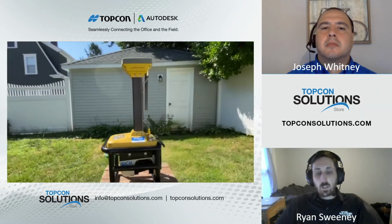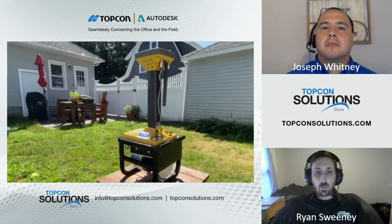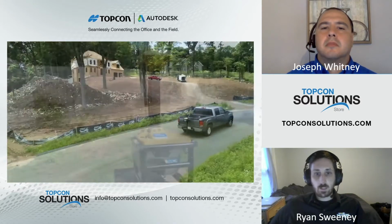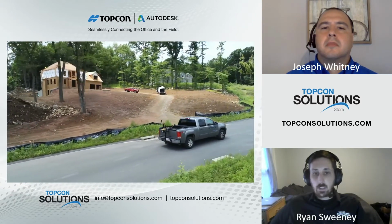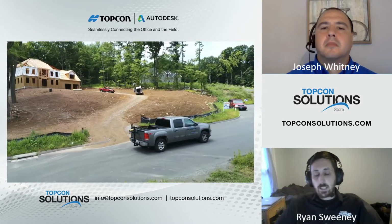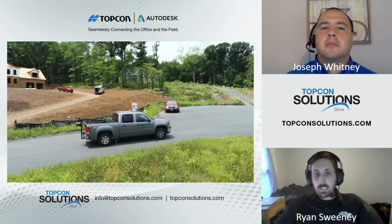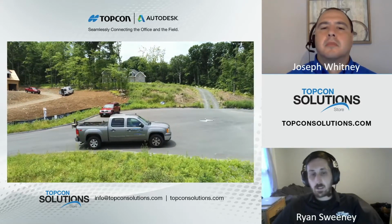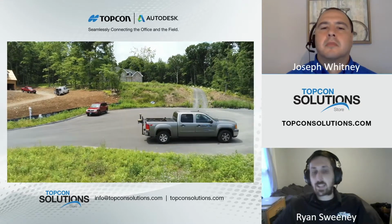Next, we're going to talk about the RDM1. And the RDM1 is our mobile mapping tool. So this is a LiDAR unit that gets mounted right to the back of a pickup truck like you're about to see here. And using GPS data and the LiDAR unit, you're driving down the road and scanning the entire road surface and getting hundreds of thousands, if not millions of points along it, which are nice and accurate.